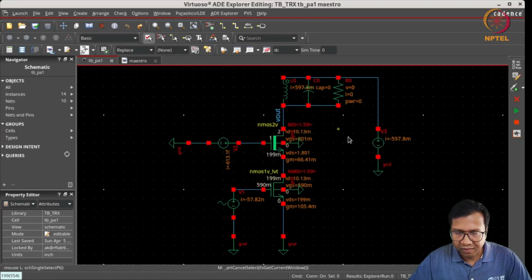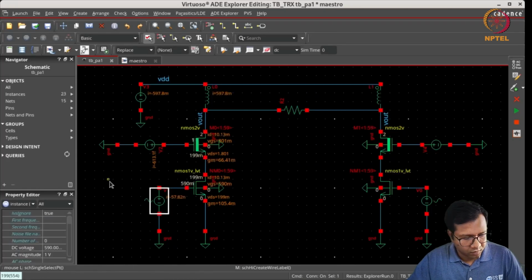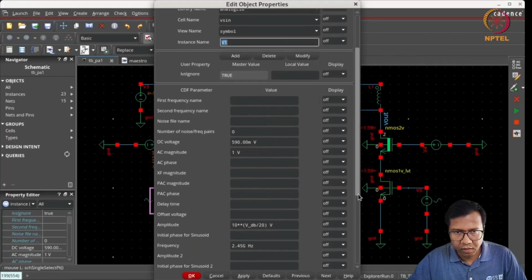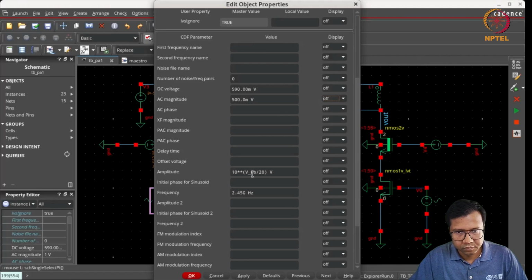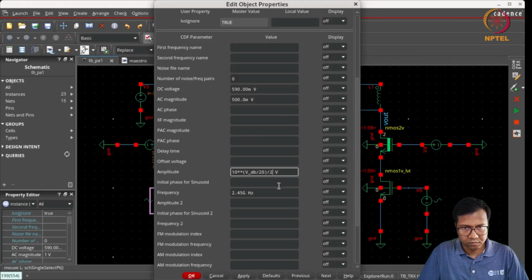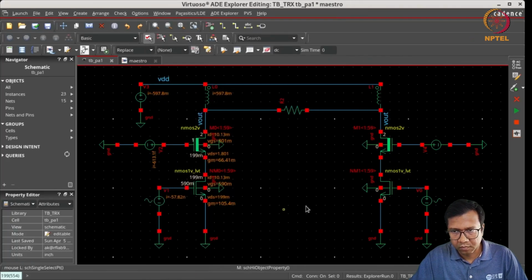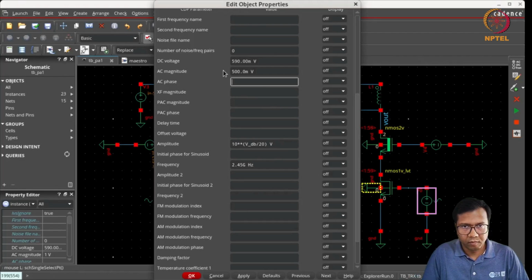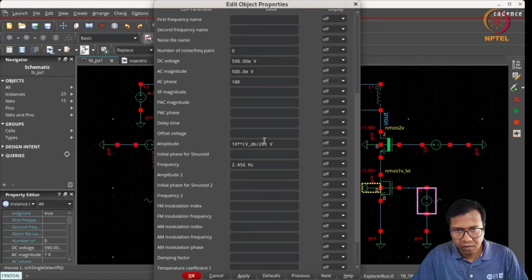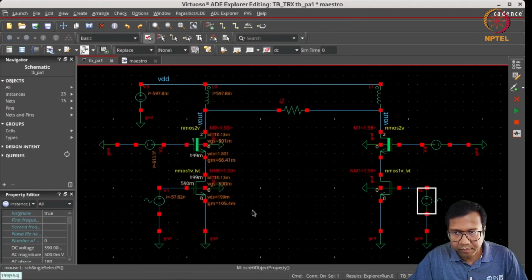So now we can just convert this circuit into a differential circuit. So now we will be applying a differential input. And here also 0.5 with 180 degree phase shift. For the HB analysis also, we will add a 180 degree phase shift for the input tone.